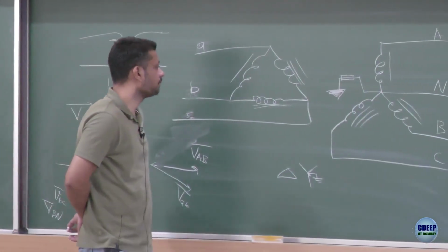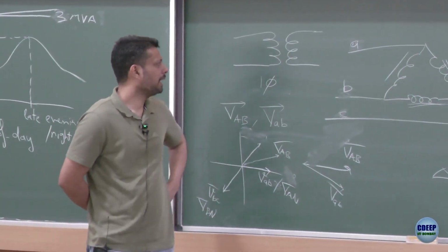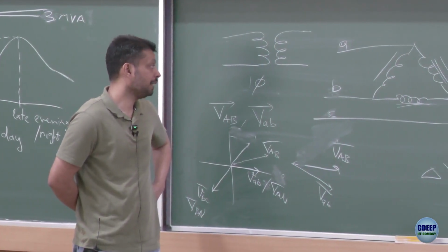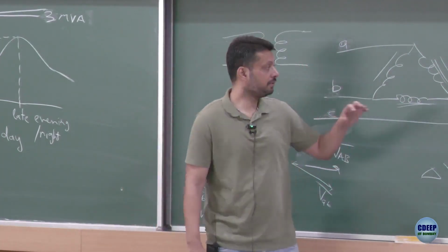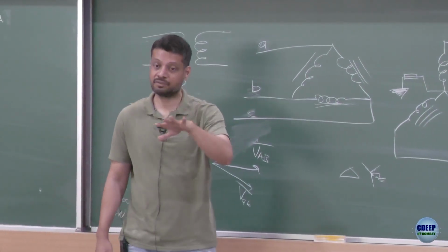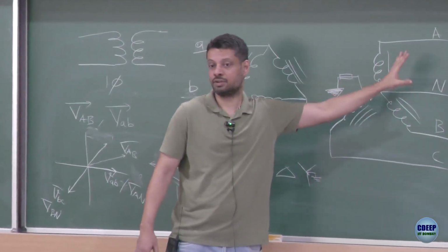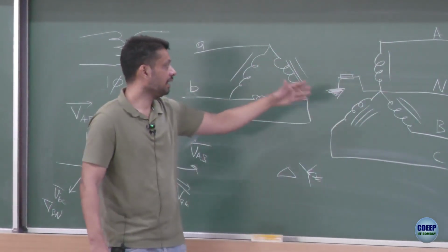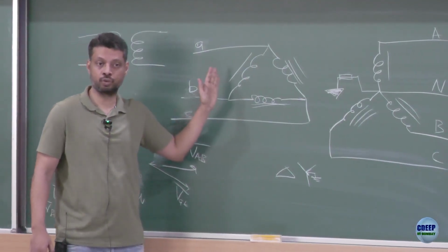Okay, so I am also not very sure, I have not really thought about it, but my very wild guess here would be that, first of all, this is something which is not covered in the course, but if you have a negative sequence component or a third harmonic current flowing here, let us say you have this A and N goes to a rectifier, there is a third harmonic current which flows there. If you have delta here, the third harmonic current circulates and it does not come from the source.